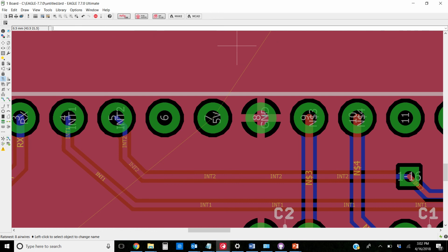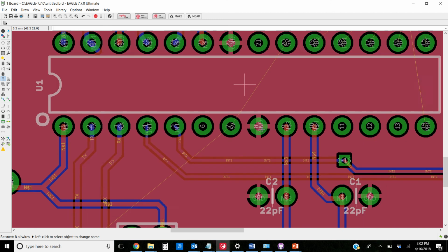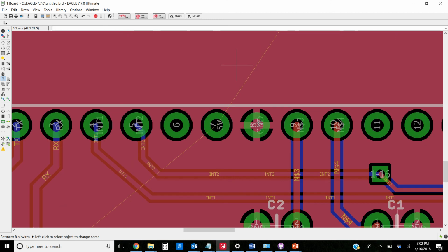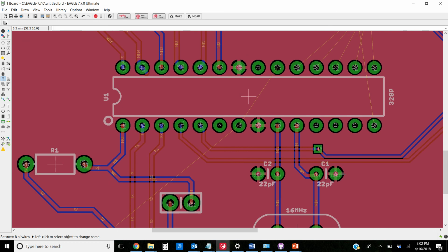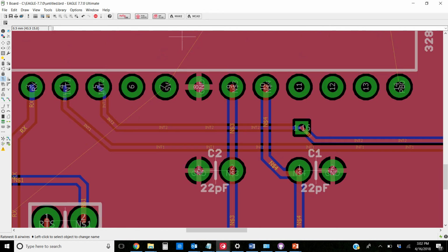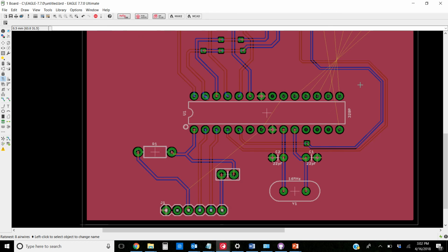So pin number 8 was our ground, and you can see it put a cross in there. And the reason for the cross is because if you put the copper touching all the sides, it can become hard to solder to that because it's going to wick away the heat in the copper plane really, really quickly. That's why they do that. But that is an option, and you can adjust these settings. And you can see it again did it on these VIAs.